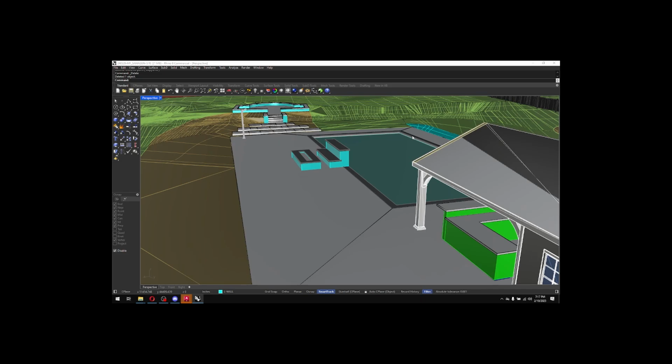I would suggest not using the live file sync with Lumion. It doesn't really help, and it's just going to slow your stuff down. So export to a DAE, then you can just refresh the model if you save over your previous one.